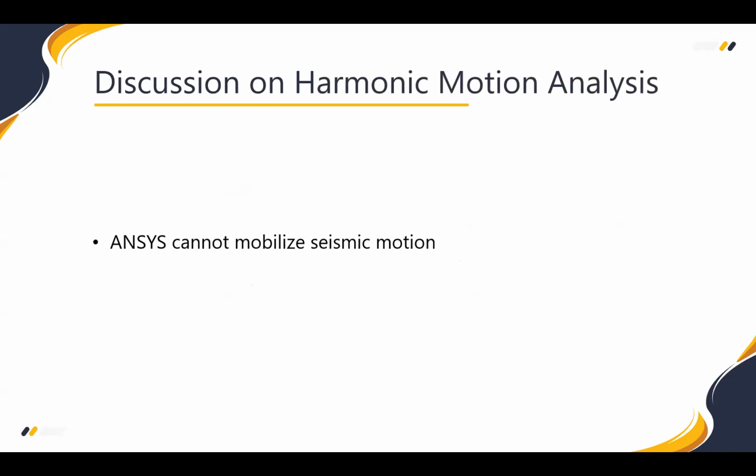Although the harmonic motion analysis of our structure generates meaningful results, there are some limitations that restrict us from investigating the soil pile interaction under seismic loading. The point is that ANSYS cannot simulate a seismic motion because an earthquake is not considered a harmonic motion, and seismic analysis requires hazard response spectra and peak ground acceleration to calculate the base shear and lateral displacement of the building.